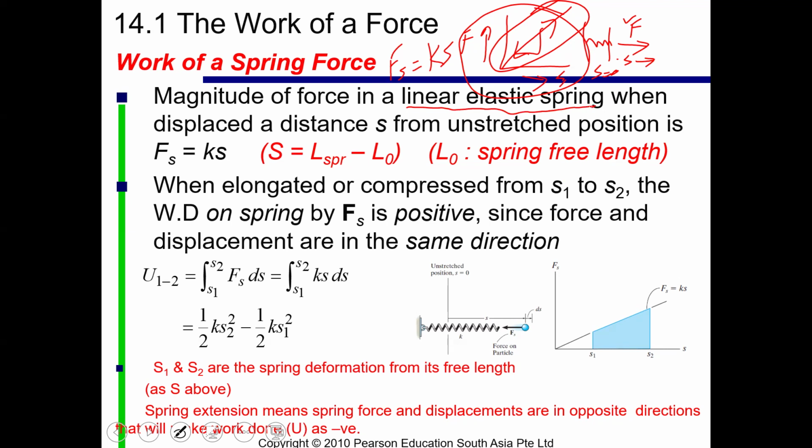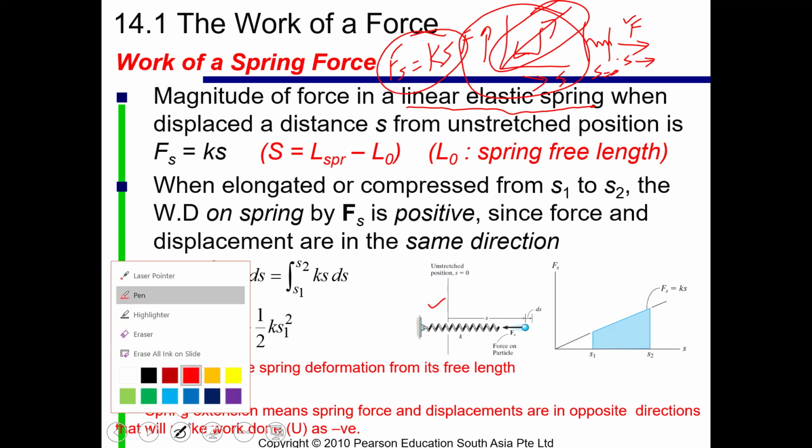However, there are possibilities by which you can also include non-linearity in springs. That's a higher topic and it's not included currently. But remember that springs can be non-linear as well, if you are dealing with a variable pitch distance or a variable coil diameter, like a leaf type spring or conical springs. Then it will be different. So in the simple scenario of the spring, as you have seen here, this is how you represent force in the spring.